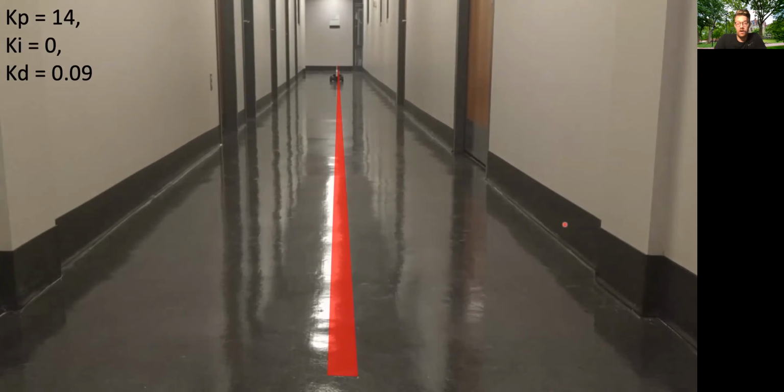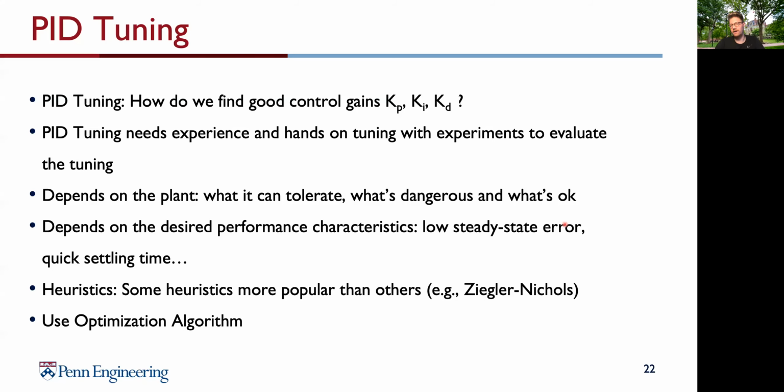So now we learned how we can set up a PID controller, but what's the magic behind PID? It's basically the tuning, which means we have to find good control gains. You remember, each of the different parts, PID, had an additional control gain, which means these are the parameters we can tune, and these parameters can vary from system to system.